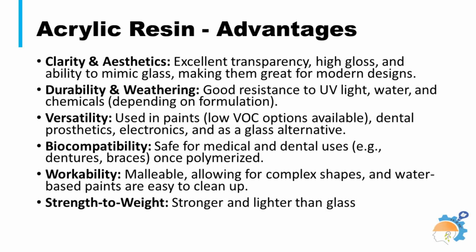Acrylic resins offer great advantages like high clarity, weather resistance, and versatility for use in dentistry, paints, and plastics. However, these face limitations such as poor scratch resistance, sensitivity to strong solvents, potential brittleness, heat deformation, and higher cost for premium types, with some formulations having odor due to VOC issues. They're popular for aesthetic appeal, durability in normal conditions, and biocompatibility in medical uses.